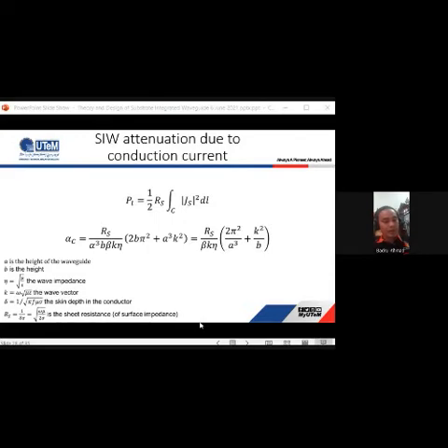But in the vertical wall, the variation is Js squared, which is the surface current density, compensated by the lengthening of the integration path C. As a result, the contribution of the vertical walls to the conductor losses is unchanged with b, and this is the reason why there are 2 terms in the expression of lambda c. The first is independent of b, while the second varies with 1 over b.